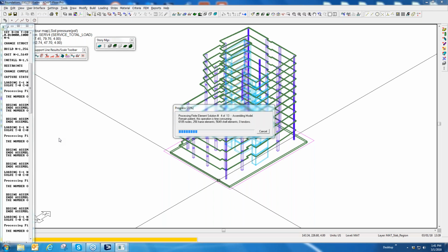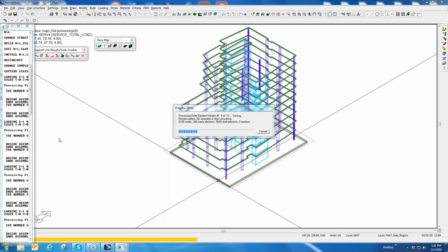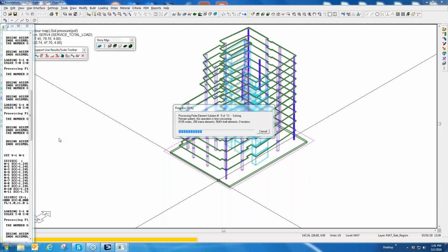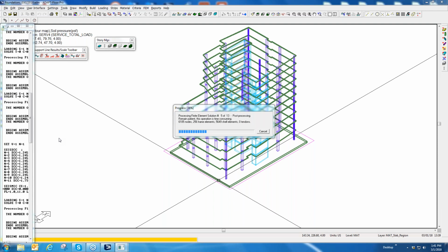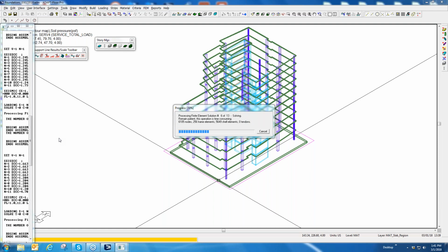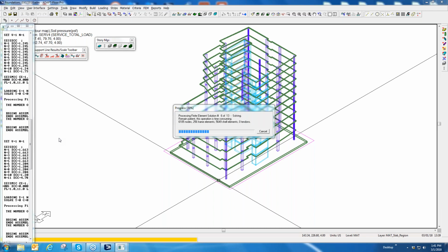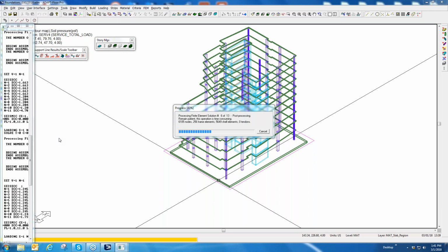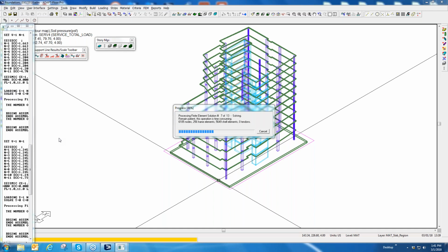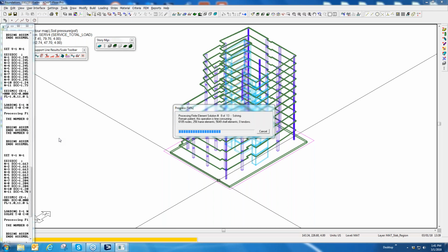And once we've run this direct solution, then we're going to talk just briefly about the design of the mat using these same types of solutions. So that will include the need for generating support lines, design strips, and evaluating those strips at either service and/or strength loading conditions. But the same general workflows can be applied not only to evaluating displacements or soil pressure, but also to evaluating or design of the mat slab for reinforcement.